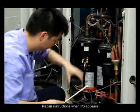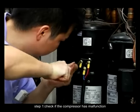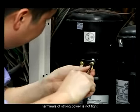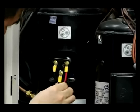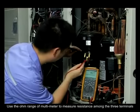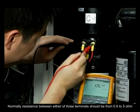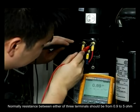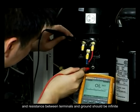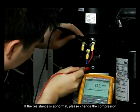Repair instructions when P3 appears. Step 1. Check if the compressor has a malfunction, a short circuit happens to the strong power, or the terminals of strong power are not tight. Use the ohm range of the multimeter to measure the resistance among the 3 terminals. Normally, the resistance between any two of the 3 terminals should be 0.9 to 5 ohm, and the resistance between terminals and ground should be infinite. If the resistance is abnormal, please change the compressor.